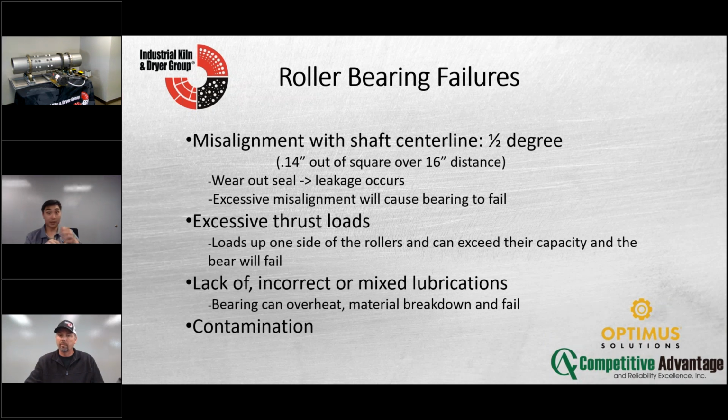If you put in a half inch of downhill on a bearing and left it, that's quite a bit of thrust. If you don't know why and you do that and then fail it, you destroyed it. Then you have contamination and incompatible lubrication, which goes back to what I was talking about earlier with lubrication coming out of the seals, with the heat and expansion.